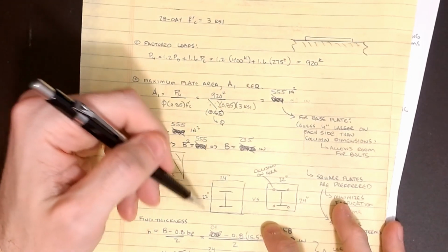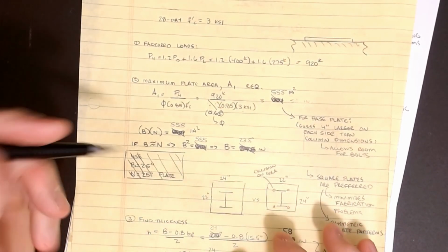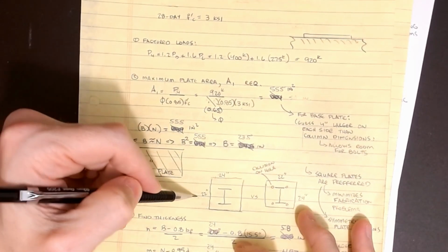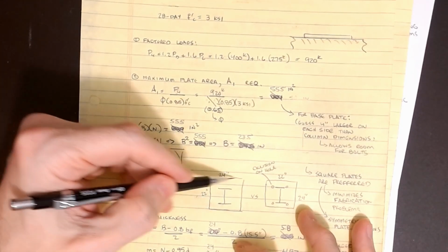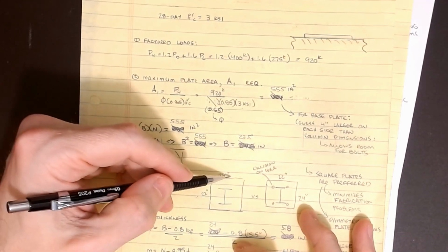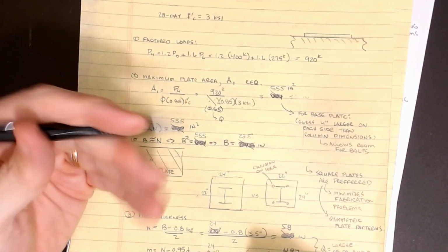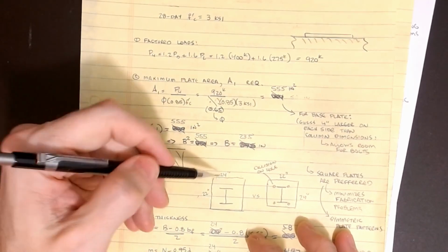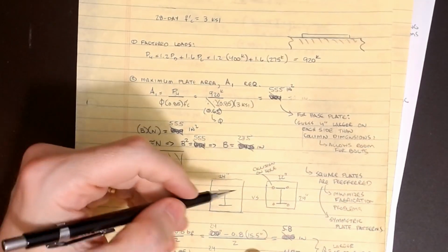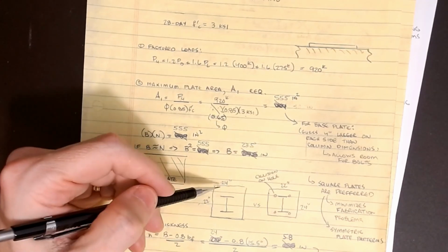In cases where you have a taller beam than you do width of flange, what you want to avoid is having plates that are very close in dimensions but not the same. If I have a plate that is 24 inches wide and 22 inches tall, that is a hard dimension for a fabricator to visually see. They cut the plate, and unless they mark the 24 dimension on the ground, these are hard to distinguish. Whereas if you had a plate that was 16 by 24, you could see a drastic difference. And this is speaking from experience, I've had plates get welded on in the wrong orientation.